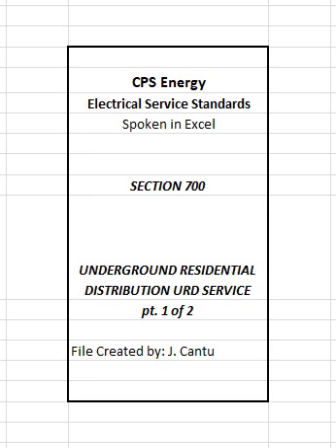4. CPS Energy approved single-phase, self-contained, residential meter sockets to be furnished and installed by customer at locations approved by CPS Energy, refer to Article 707. 703 Transformers. CPS Energy will determine the number and location of pad mount transformers that will be installed in a URD system. Customer shall furnish space meeting all clearance and easement requirements for each transformer and shall allow it to be readily accessible.